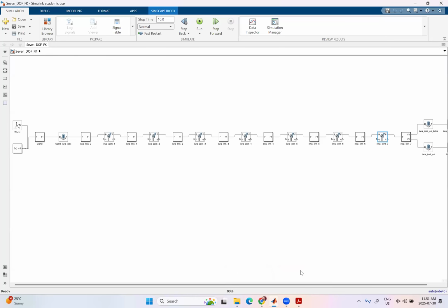But the next step is, okay, I told you in Simulink, we are dealing with signals that are not understandable for the multi-body simulation part. The multi-body works based on the fact that either you need to provide it with force, torque, radiance, and so on. If you generate a signal, MATLAB doesn't know what that signal is, or what signal you are generating. So for that purpose, we need to employ a converter, which is called PS to Simulink converter. Sorry, Simulink to PS converter.